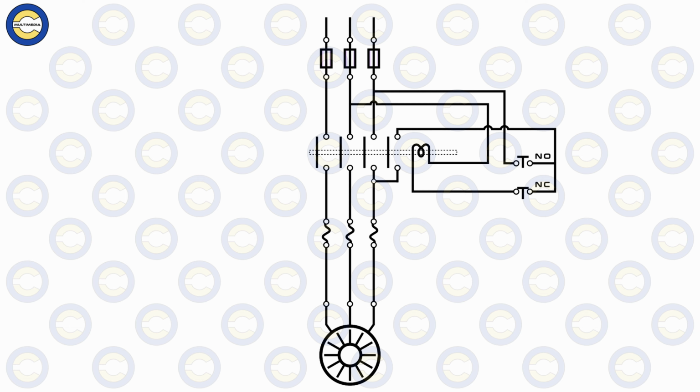What this will do is damage the windings of the motor due to excessive heating, by virtue of the extraordinarily large starting current drawn. It will also trip the circuit breakers and cause voltage dips in the ship's electrical network. This can be very dangerous, especially for critical or essential machinery like the steering gear or when the compressors are running. This is the primary reason why we use starters to ensure smooth and safe starting and stopping operations of a motor.